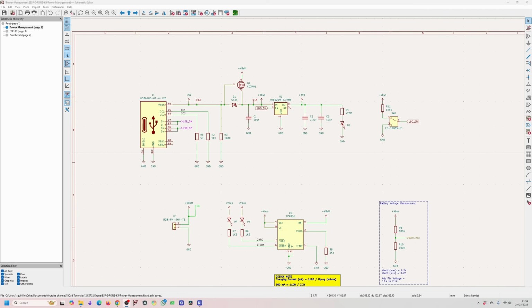This saves time, improves consistency, and prevents design errors, especially if you're working in a large team where communication might be difficult. So with net classes, you can tell the PCB designer, which may be yourself, what kind of clearances a net needs and what kind of track needs to be routed. So for example, let's say you have a USB data line, then that will need to have a 90 ohm differential impedance, and you want to relay that information to the PCB design side as well.